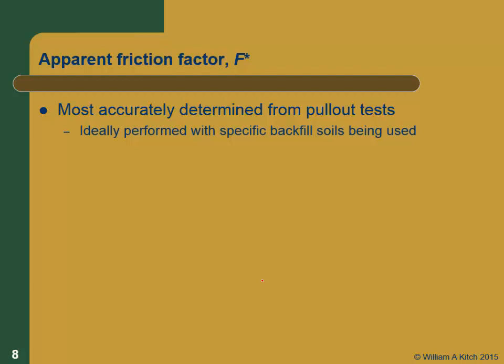But if you're doing any significant construction, it definitely would behoove you to pay to have the pull-out tests run on the backfill material you actually plan to use. Unless you want to be explaining during the lawsuit after a failure about why you didn't do that.